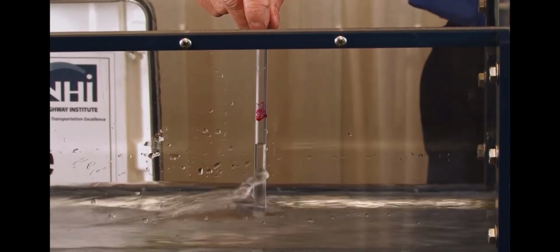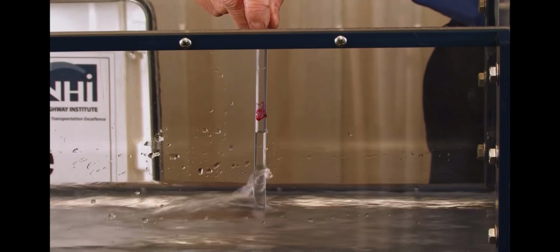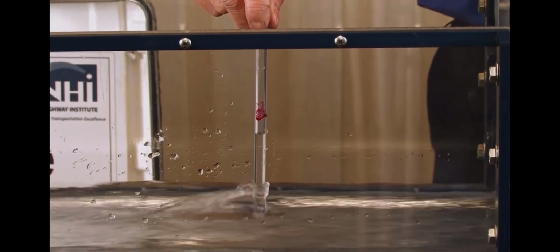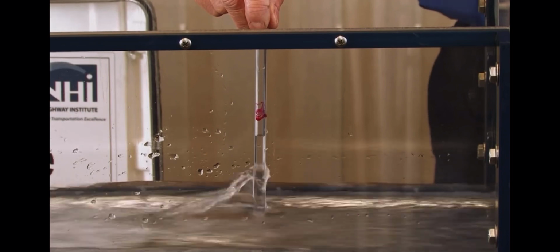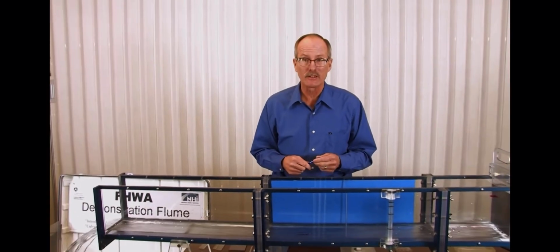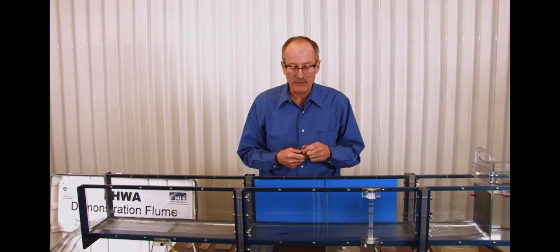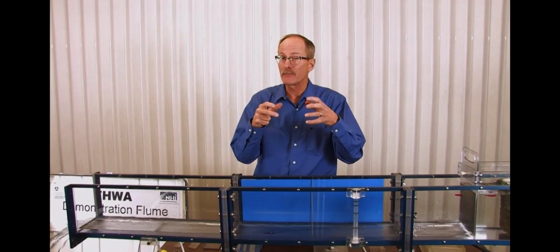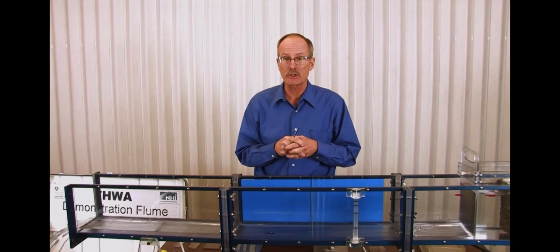Sloping downstream and dropping quite a bit, reflecting the friction loss. Between these same two sections, the hydraulic grade line doesn't change nearly so much. In fact, it's simply the water surface, and since we're pretty close to steady uniform flow, it'll be the same as the bed slope. So the differences in the hydraulic grade line, which is something we often plot on our storm drain plans, is important because what it represents is how high the water might rise above the top of the conduit if it goes under pressure.